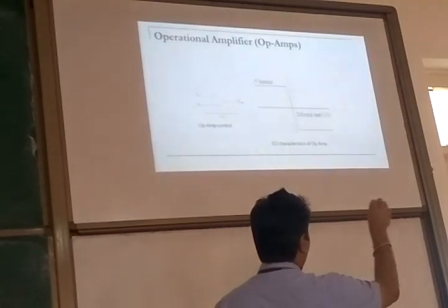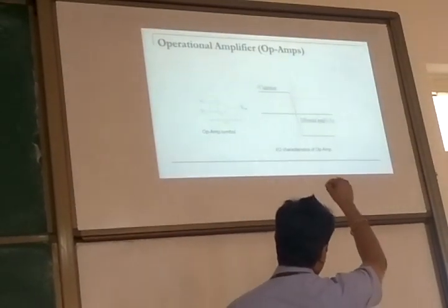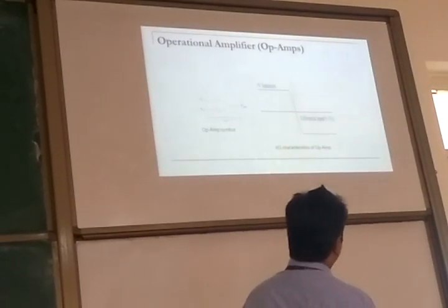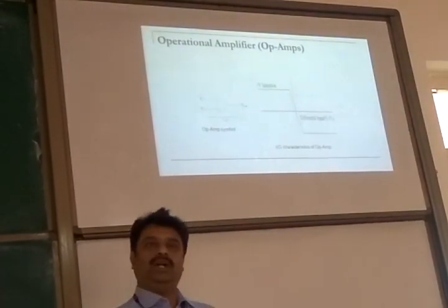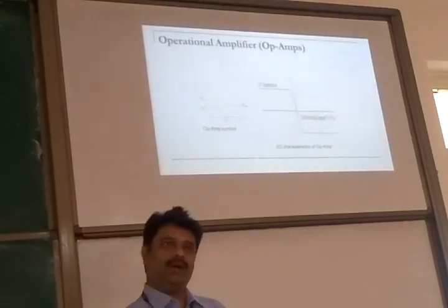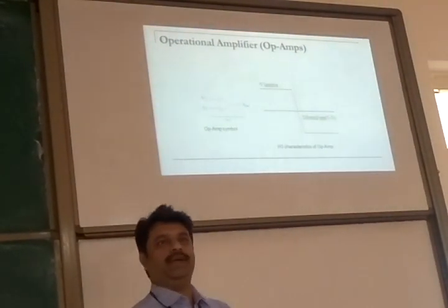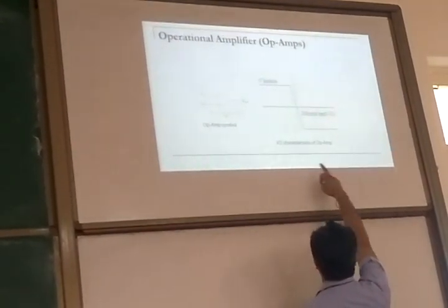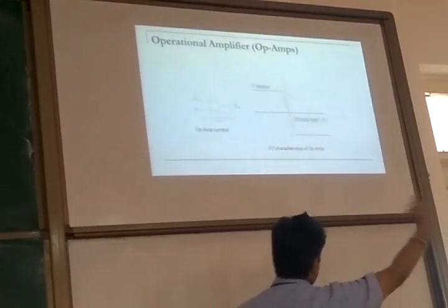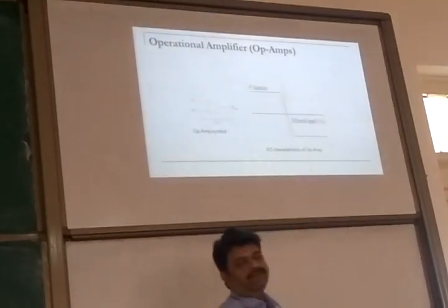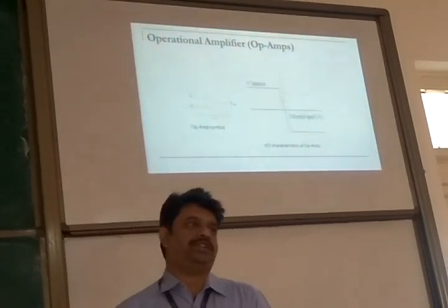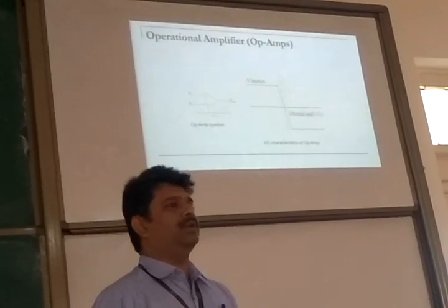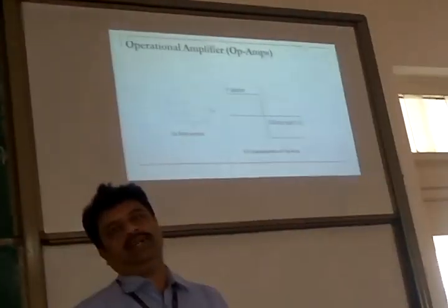And if the differential input is positive, on the right hand side of the vertical line, you get a negative output. Okay, and that reaches the so-called saturation, the horizontal line on the right hand side. You see a horizontal line. That line is called the saturation point. That means the amplifier will no more be able to give output beyond that voltage.